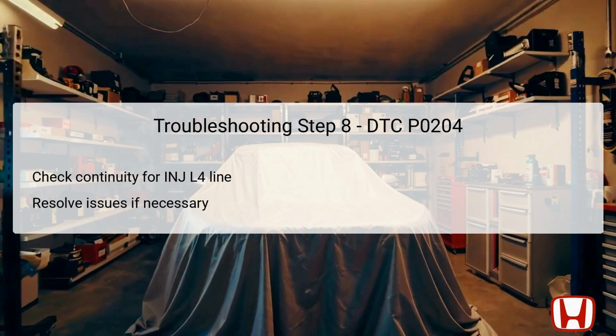After this, you should consider consulting any authorized service information relevant to DTCs or symptoms you are troubleshooting in case further exceptional procedures are required. If the PCM, Powertrain Control Module, has been substituted and DTC P0204 clears, this indicates it was the fault, and the original PCM should be replaced.